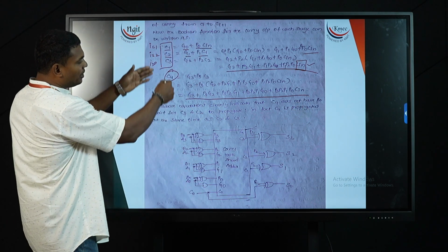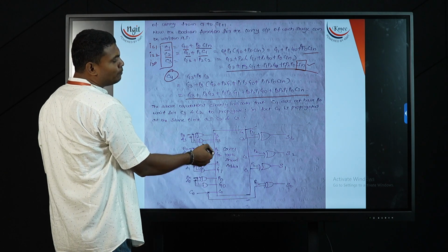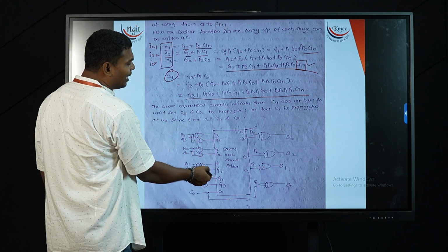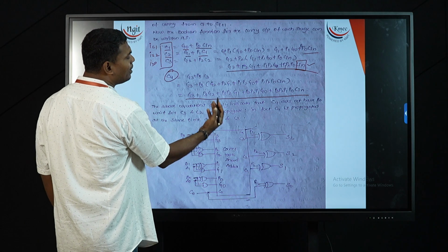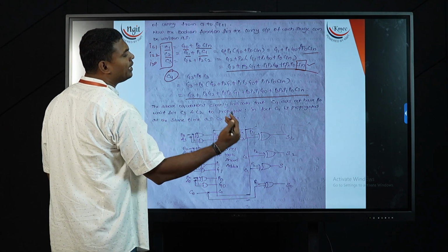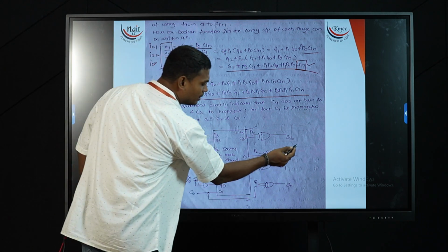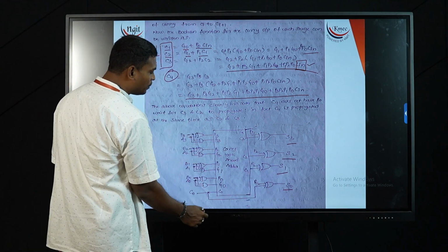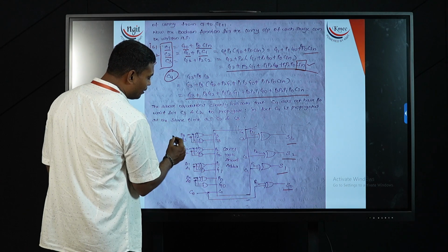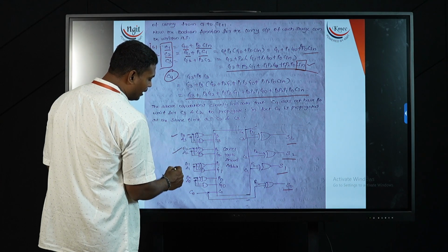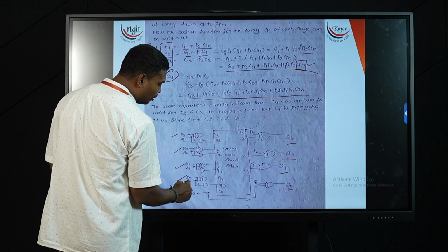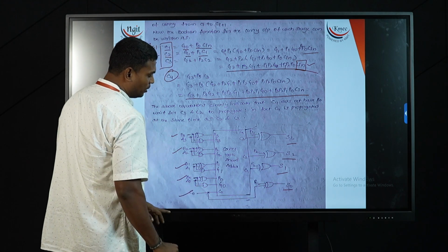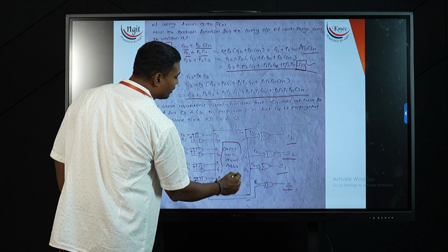So based upon these equations, we can prove that the carry generation and propagation is not needed for generating the sum values, that is S3, S2, S1 and S0. So using those expressions, I can directly connect my A3, B3, A2, B2, A1, B1, A0, B0 and initial stage carry C0 to a carry look ahead adder.